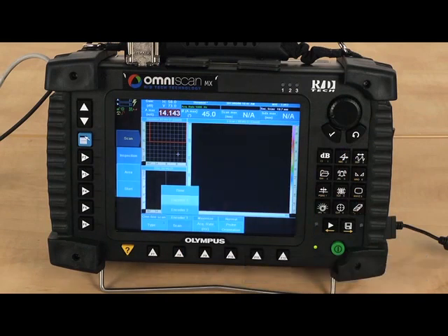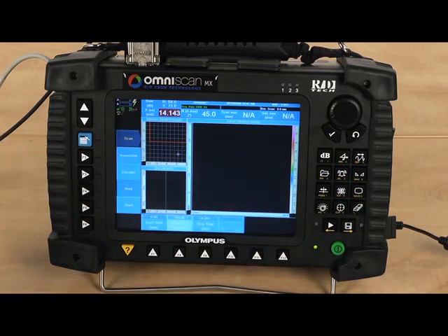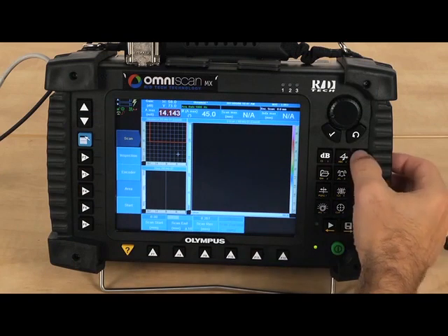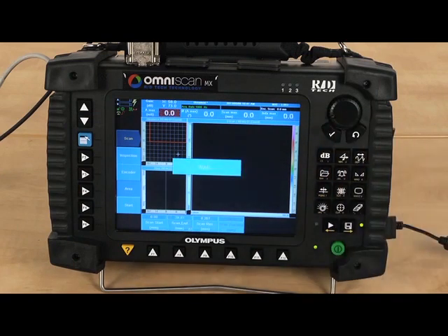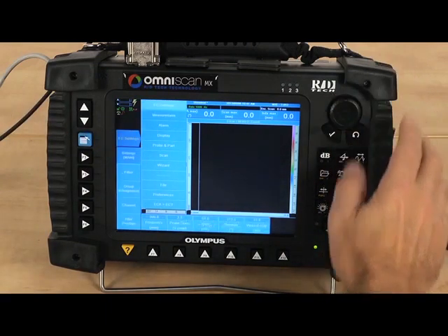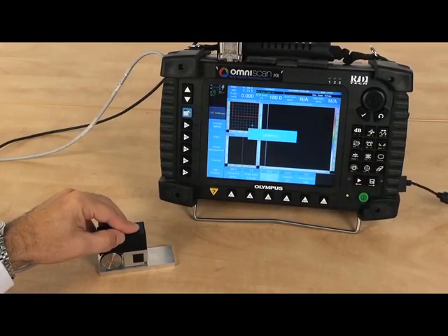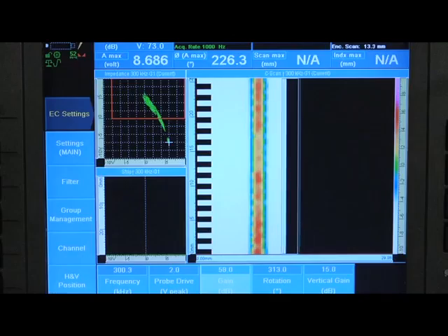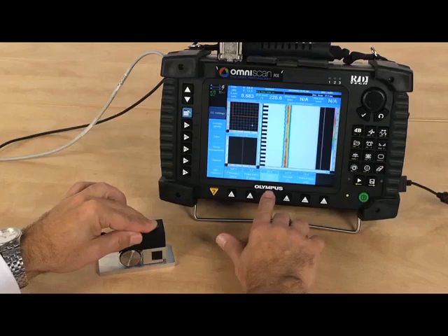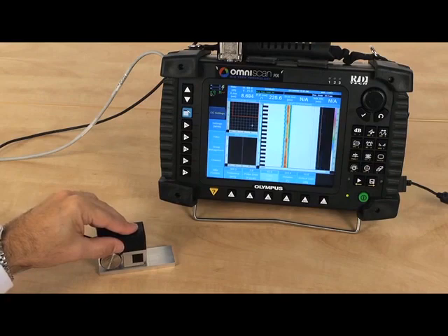To activate the continuous mode, select Continuous. Select Area, select Scan In, and then enter the probe size value and press OK to accept. Select Menu, select EC Setting, and then Setting Main. Now we are ready to scan the defect and assess the resulting image. Press the balance button and scan the standard. Some final gain adjustment may be required. If necessary, add up to 6 dB and rescan until you have achieved the ideal color and contrast.